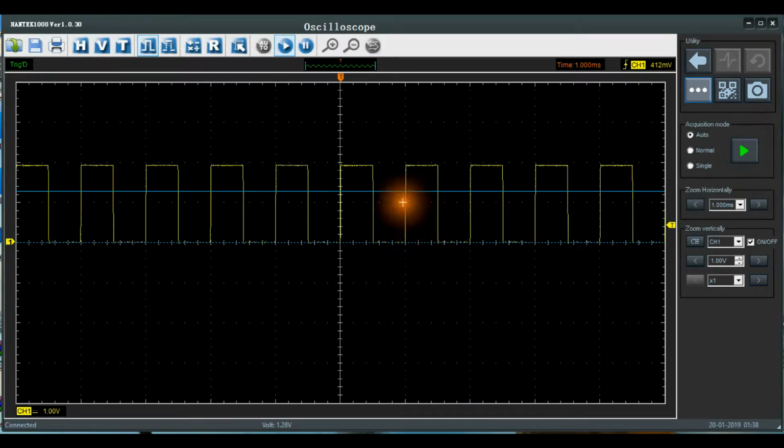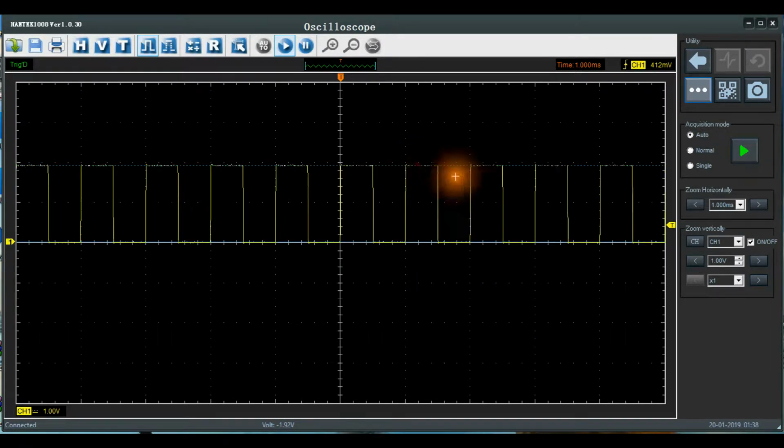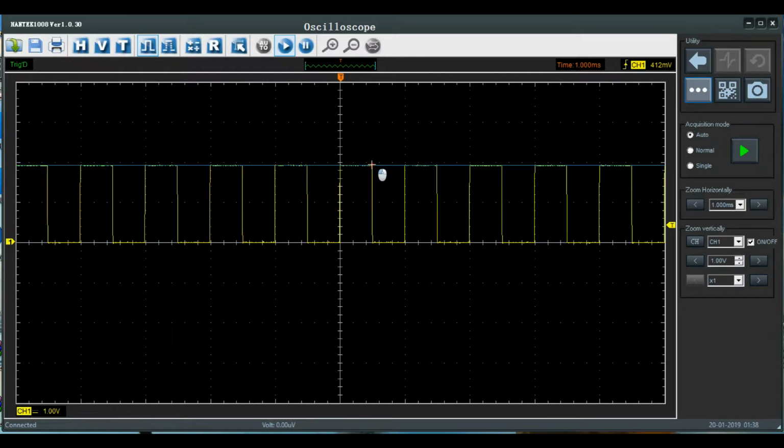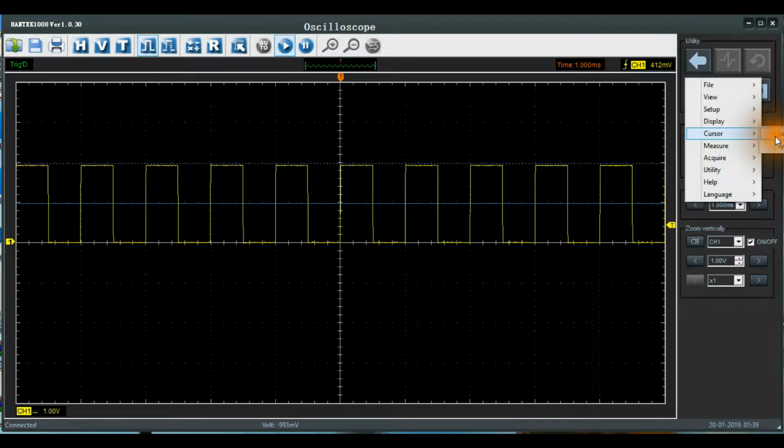So if I come here, and let's just say this is my 0 line, and now I'm going to put from there to there. I got 1.92 volts, which is pretty close. Actually, I could bring that up. I'll bring that up. There, and we'll bring it down. And 1.196. That's the voltage of my waveform, the max voltage. And that's what the horizontal cursor will give you. Now, that's for your cursors. So your cursors are right there. So we're good with that.